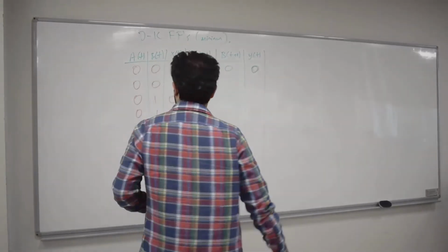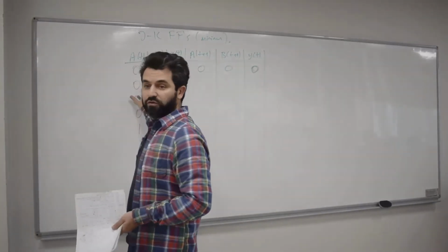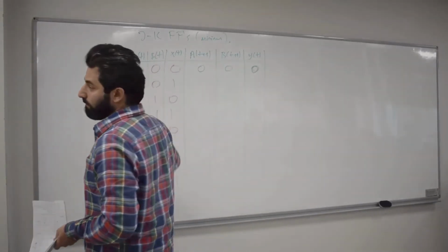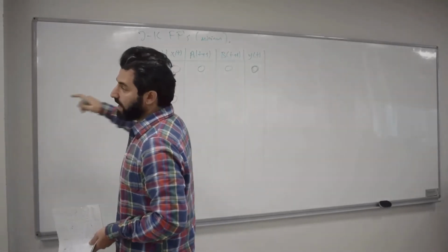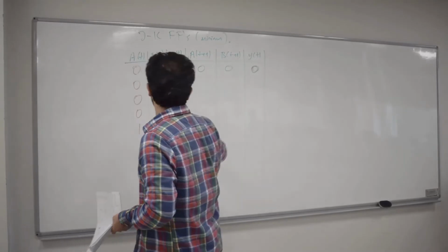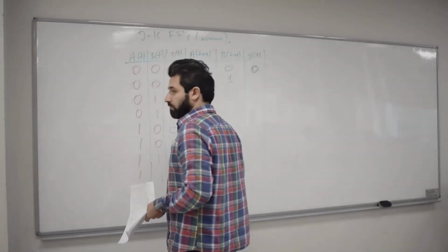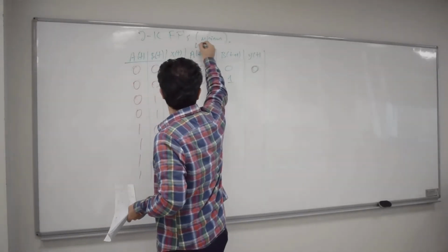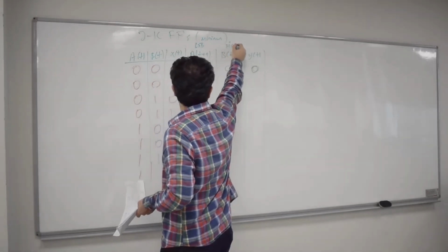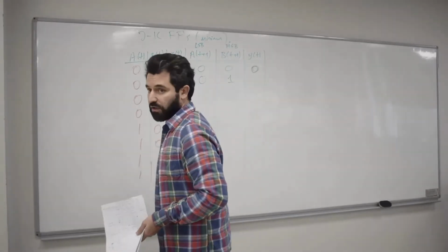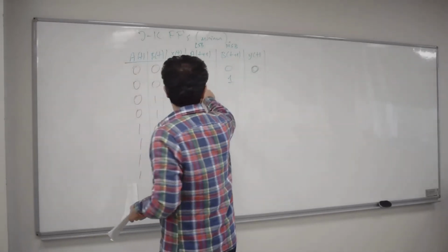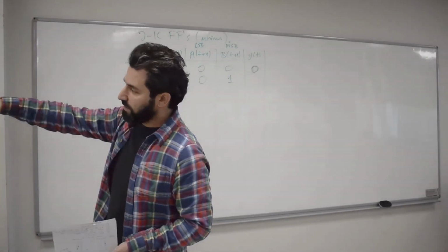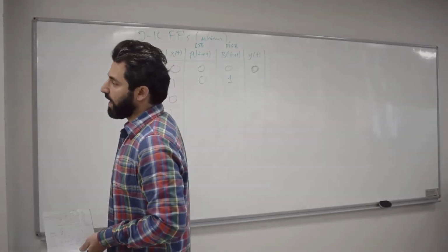Okay? And when you have 0, 0, that means you're in A, and you have an input 1, okay? Then, as you can see, you move on to 0, 1, this is my first bit LSB, and this is my MSB. Least significant bit, most significant bit, in that representation of bits. So I move on to 0, 1, as you can see, which is the state B, and output is 0.